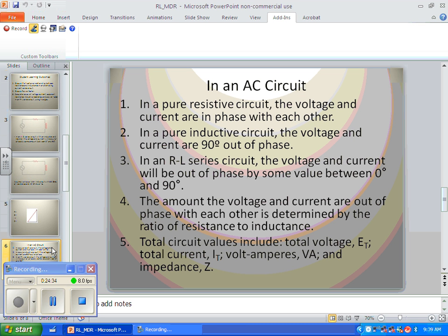Okay, that's sort of true, and it's mostly true, but not necessarily true. True power is always additive. Apparent power, not always. So remember, the thing that you found easily in the first semester was apparent power, but that doesn't add up perfectly every time.